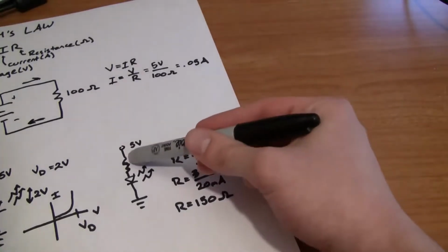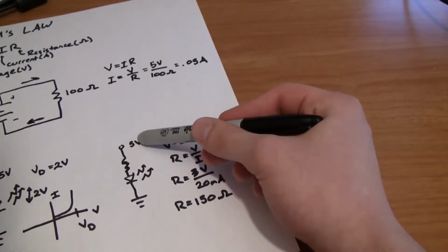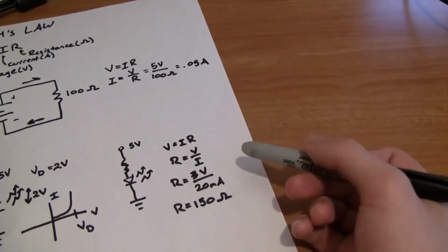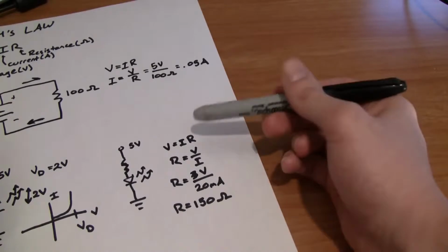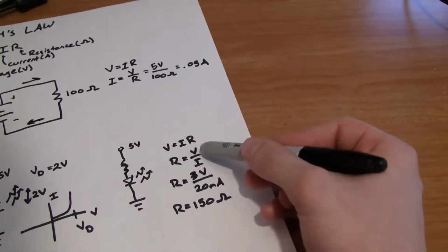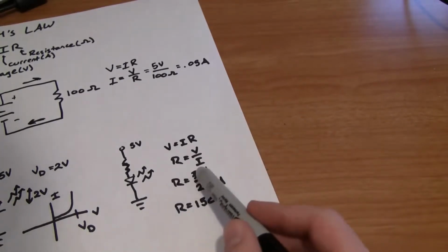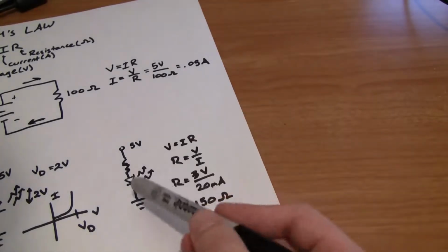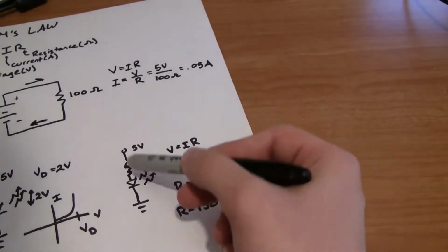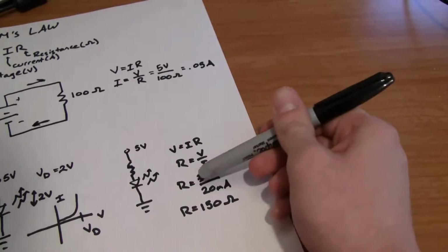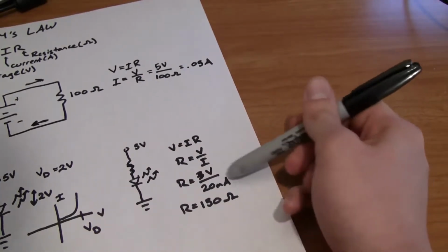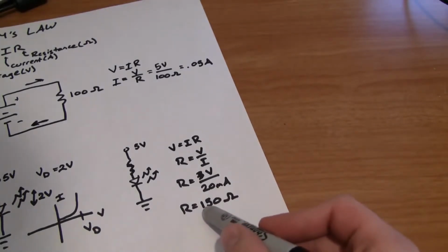So let's figure out what resistance we want that to be. If we have a 5 volt supply, and we want 20 milliamps of current going through the LED, which is a pretty standard amount for it to glow at a good brightness, we'll want to use Ohm's law to figure out what the resistance should be to accomplish that. So resistance equals voltage over current. We have 3 volts left because 2 volts will drop over the LED on its own. So that gives us 5 minus 2, which is 3 volts to drop over the resistor. So we want to drop 3 volts over the resistor, and we want 20 milliamps of current to be going through it. So if we divide that out, we get that the resistance should be 150 ohms.